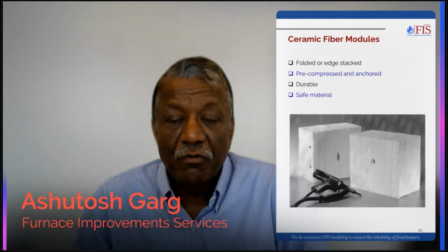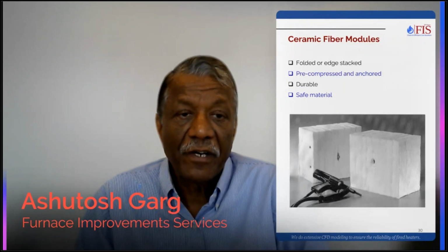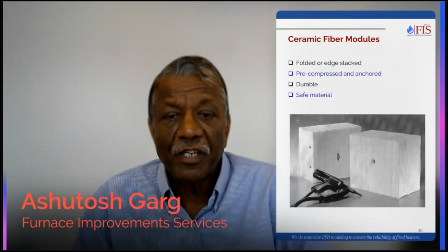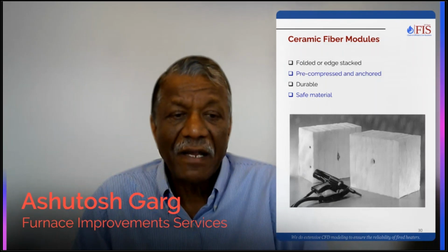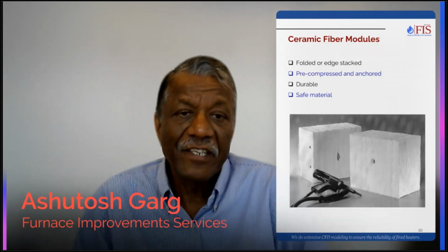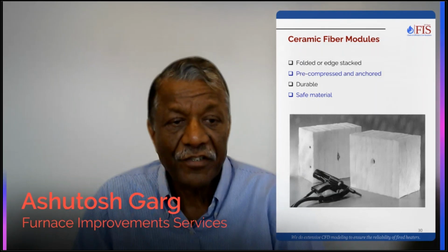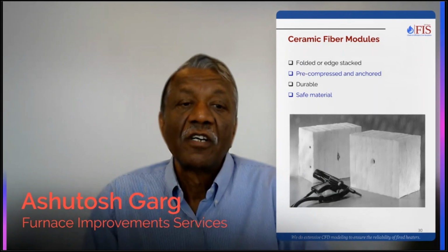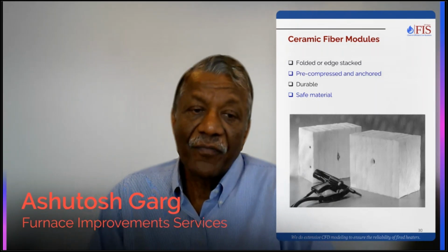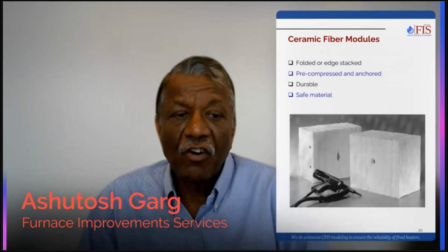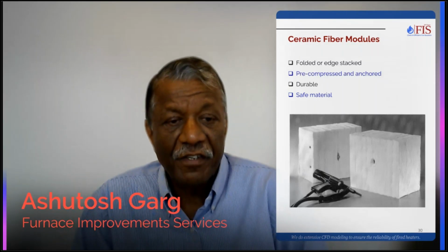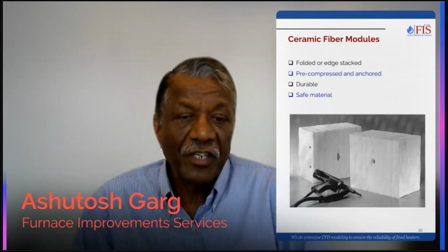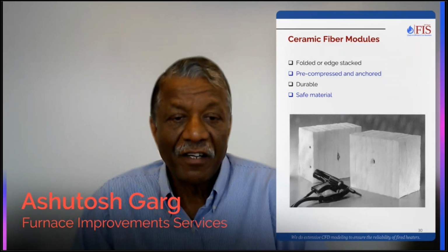Ceramic fiber modules is a very popular material. These modules are prefabricated using blankets, and these blankets can be folded or edge stacked. This one is edge stacked, you can see, and then there are other ones which are folded, one, two, three, four, and then they are pre-compressed and anchored, and they have become a very common means of installation of ceramic fiber because the installation time is very fast.